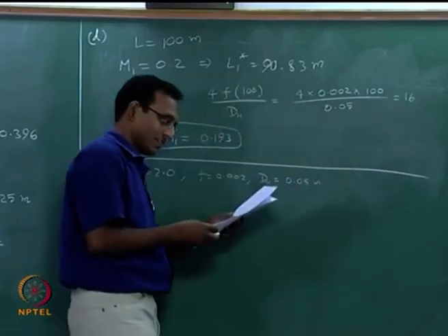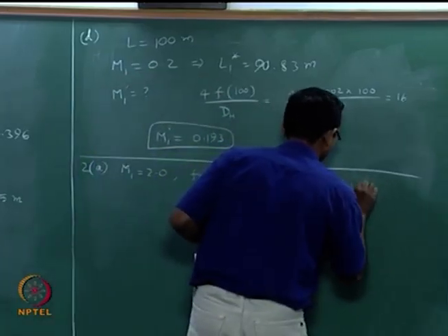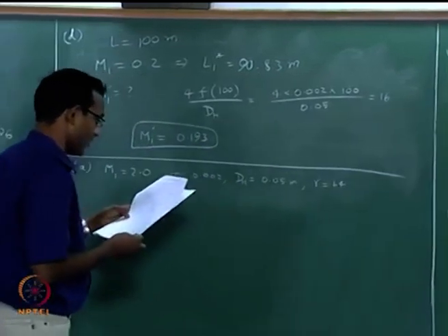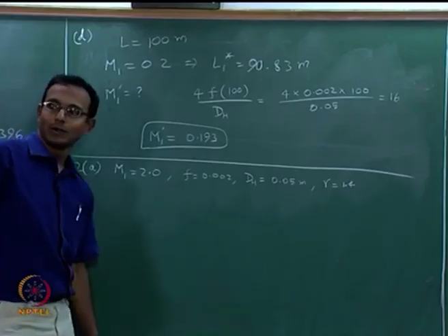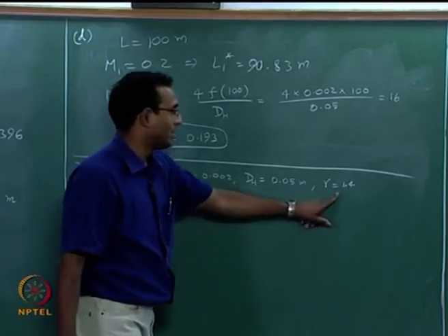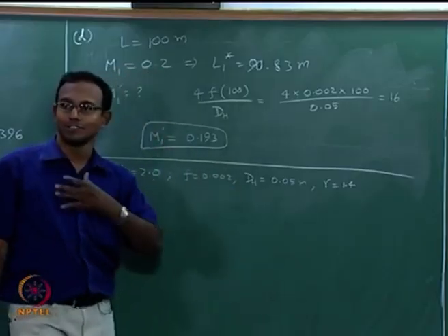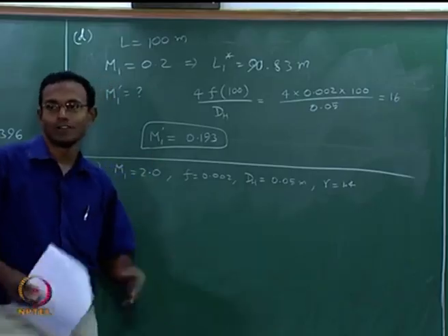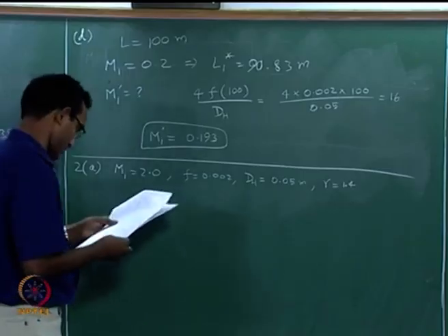Of course I will give you another exercise with all these numbers varying. Not very difficult to calculate, but it is just something you have to get used to. With these numbers you can make a mistake. Typically in looking up tables, the gamma can be different in different books. Some books will give you different tables for each gamma value. You should not look at the wrong gamma value, or you will get all wrong results. Typically this is the mistake made by most students.